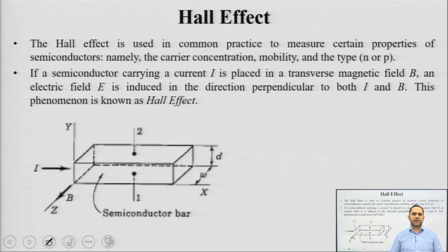So, the total current inside a semiconductor is composed of drift as well as diffusion, and drift can be produced by both electrons and holes in the presence of an external electric field. Diffusion can also be produced by both electrons and holes in the presence of a carrier concentration gradient. And we also discussed topics like conductivity, resistivity and mobility.